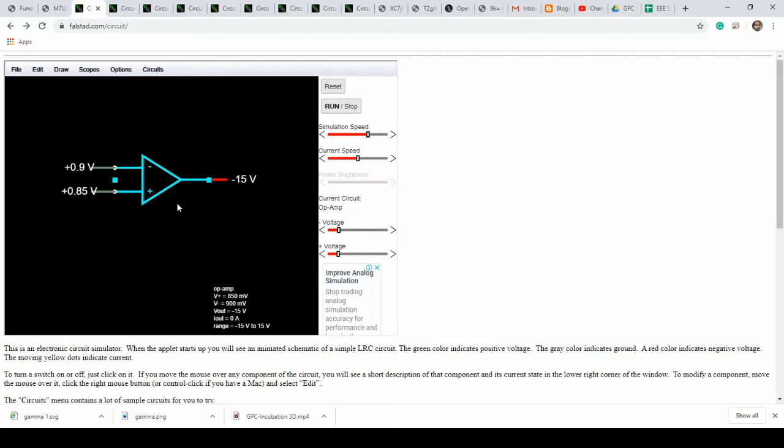It's your power supply, your plus 15 and minus 15 that you connect to it. So what does it do? It's a differential amplifier. In other words, it's got two differential inputs, and based on this input, the output switches between logic high or logic low, plus 15 or minus 15 or 0. So okay, logic of high, low, or 0.